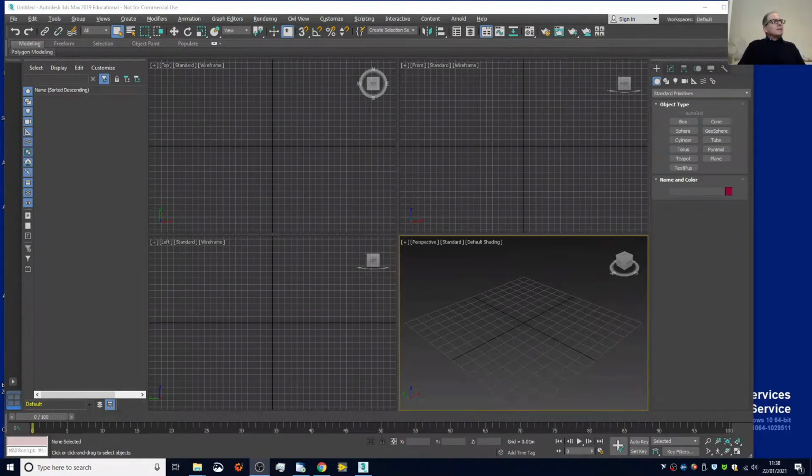So you have to think about what we've done so far with the robot arm as forward kinematic. We learned that we can have parent and child, and that when we move the parent, the child move around. So we have the fingers are the children of the wrist, of the forearm, of the elbow, of the arm, and the arm of the upper arm, and the upper arm of the shoulder. I'm confusing my shoulders and my elbows. And so when we rotate the shoulder, all the arm rotates. When we rotate the elbow, all the forearms and the wrist rotate. When you rotate the wrist, the fingers move, and so on and so forth.